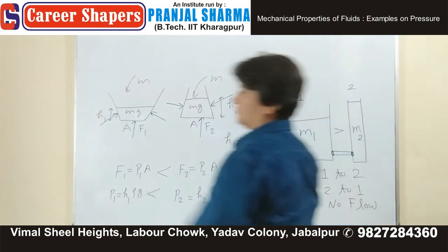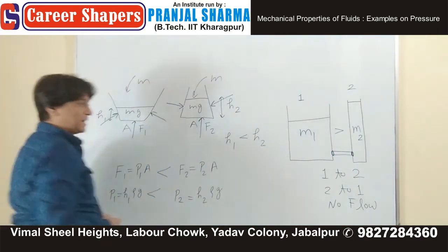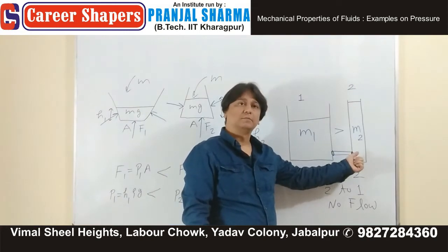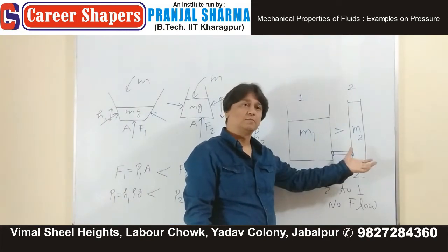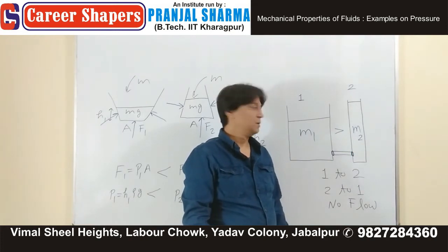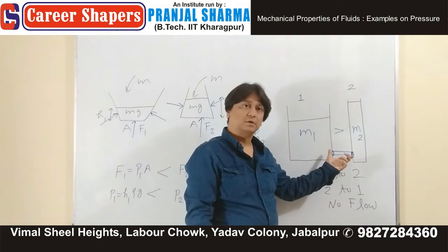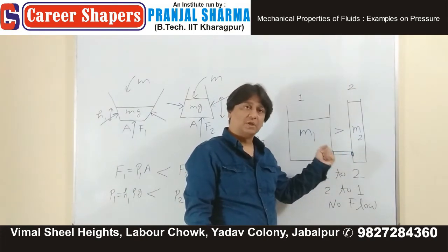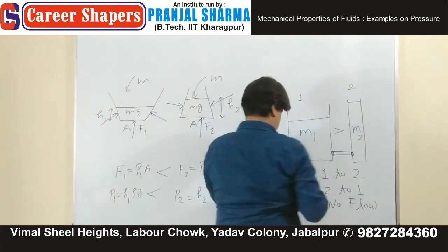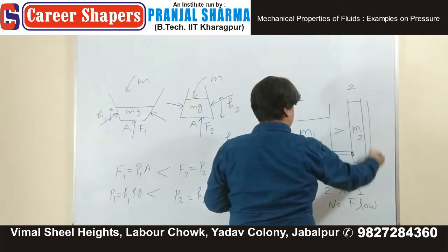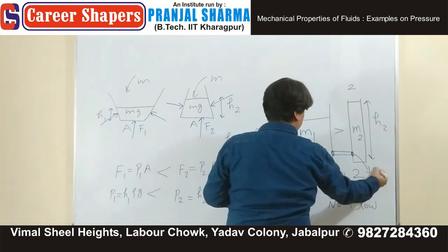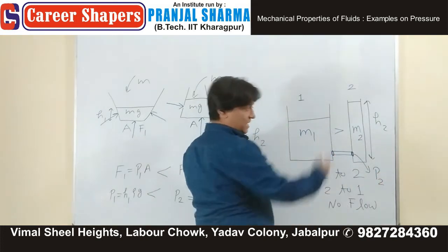Good. Almost everybody has answered correctly. It has nothing to do with the amount of water. Nothing to do with the amount of water. Everything is based on what? Pressure. You're moving things with the help of what? Pressure. In this case, this is the height. You have more pressure, P2, you can see H2 rho g.